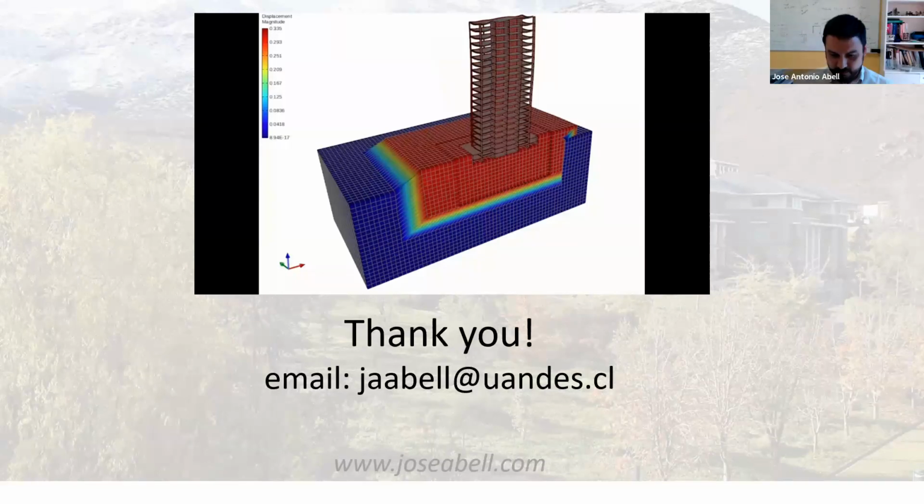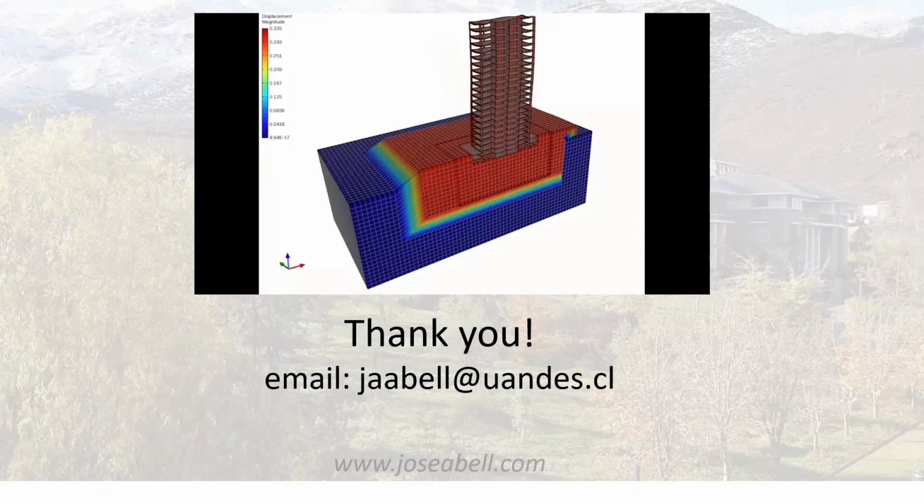Okay, but Sukumar was asking, do I mean numerical damping coming due to numerical reasons in the last slide? Sorry, I didn't catch which one this was, but I was probably talking about the damping of the DRM layer in that case. If it's not that, maybe you can tell me if that's what you meant. But it's not numerical damping. It's an additional physical damping that you're using to model the seismic radiation in that case.